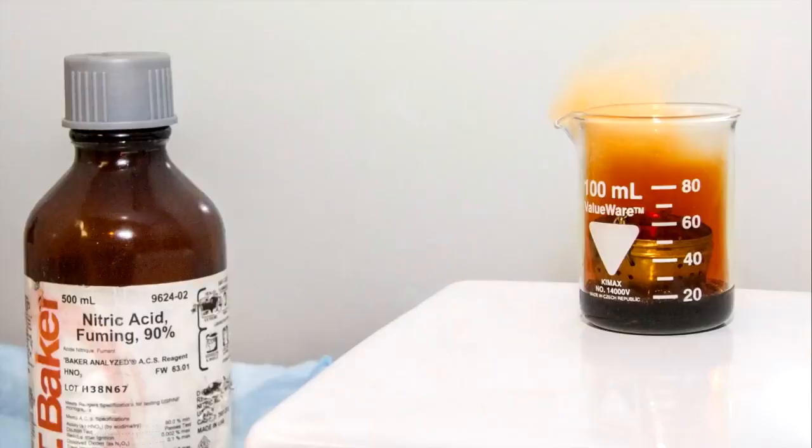To look at the chip under the microscope requires that the chip is decapsulated. Fuming nitric acid is used for this. The chip is immersed in heated red fuming nitric acid, which reacts with the plastic packaging and removes it. The chip is then rinsed in acetone and cleaned with isopropyl alcohol in an ultrasonic bath, which leaves the die bare and clean. The nitric acid is quite aggressive, and it's important to handle it carefully, but the process is really straightforward. Most people probably wouldn't want to do this in their home, so you should go out to the garage and use your fume hood there.